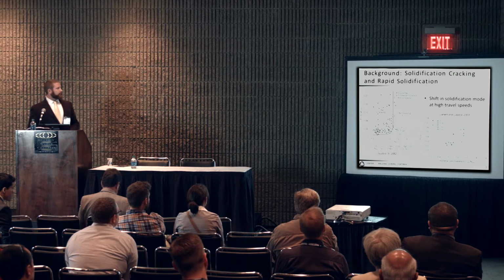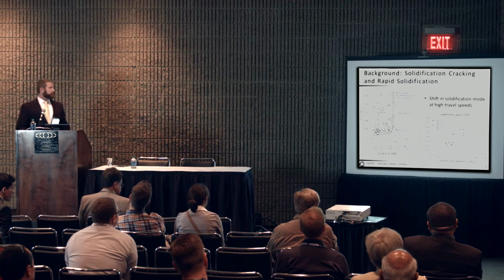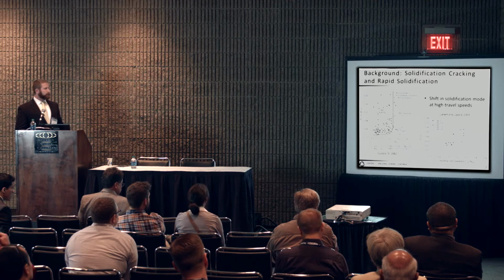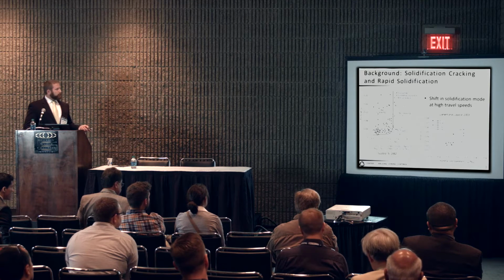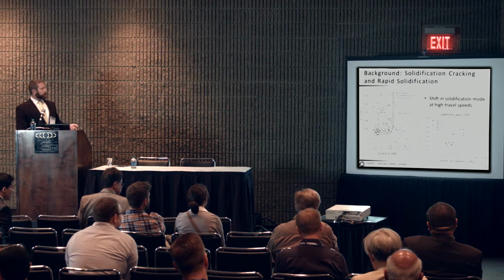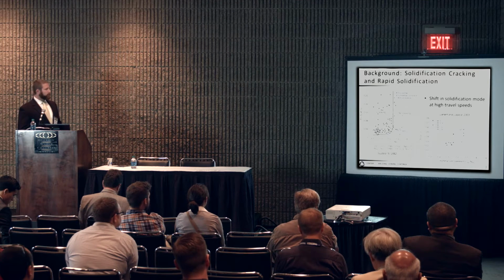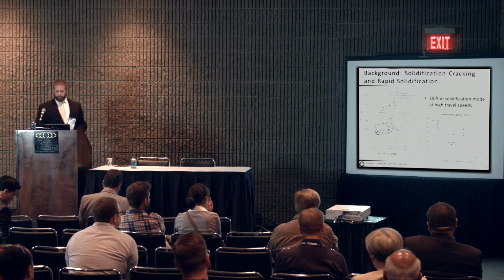Then as high energy density welding became more prevalent, it was observed there's a shift in solidification mode due to increased undercooling at high travel speeds and the high solidification rates you get at high travel speeds. So with that, there were some different weldability diagrams developed for laser welding. This one in particular is for pulse laser welding, and we see the critical chrome over nickel equivalent shift from about 1.5 to 1.6 to 1.7 due to the increase in solidification rate.